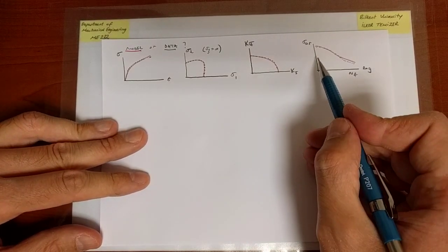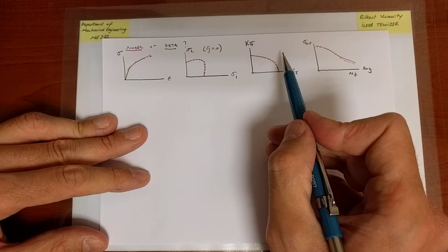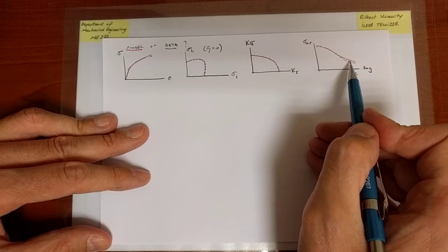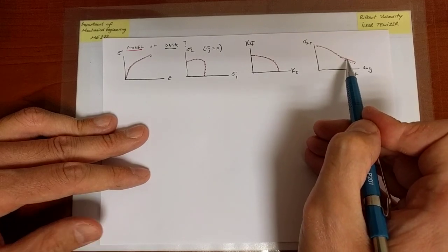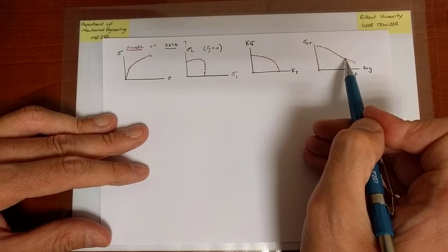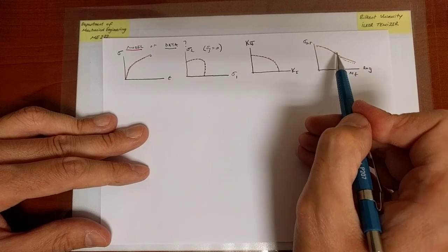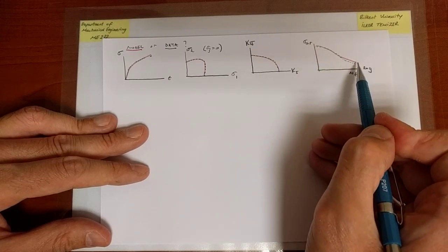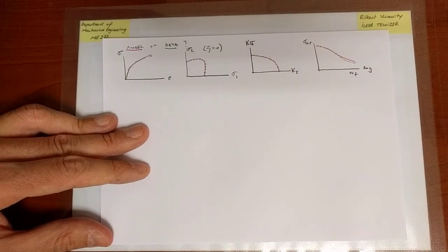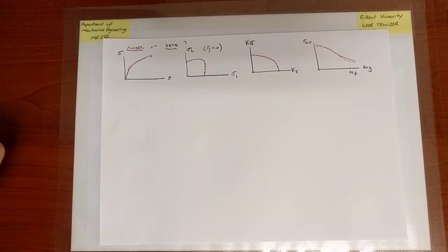the fatigue strength. But in reality, first of all, there is a lot of scatter in the data, considerable scatter, so it's not very clear which is the best point to take. For a given life, there will be multiple strengths, close or a little bit far from each other. And two, you won't have that many data points. You will have only a few data points. So it's good to always have a model that can give you a meaningful estimate, that is, let's say, the best estimate based on the data available. So that's the purpose of a model.